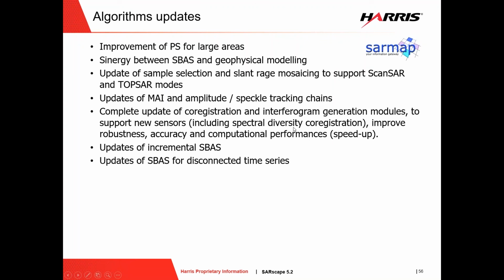But very important was a very deep update of the co-registration and interferogram generation module to support TOPSAR acquisitions, spectral diversity co-registration, very precise, and all the module has been significantly rewritten, so we improved a lot in terms of robustness, accuracy, but also in terms of computational performances. So there has been a significant speed up of the module.